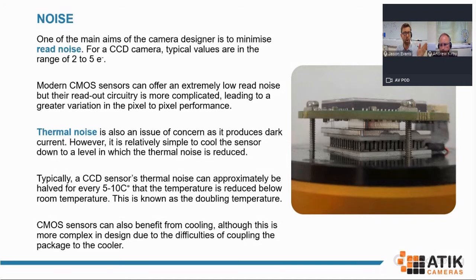So that conversion from charge to electron through to a digital format at the end will create noise as it goes through that process. Now with CCDs, fortunately, well, from a statistical perspective, that noise is created in a fairly normal distribution. So it makes it easier to calculate and then give a more, let's say, exact value. And in most CCD sensors that you'll see on the market, that's kept down below 6. You'll see sort of 2, 3, 4, 5 as a value there for the read noise levels on those cameras.